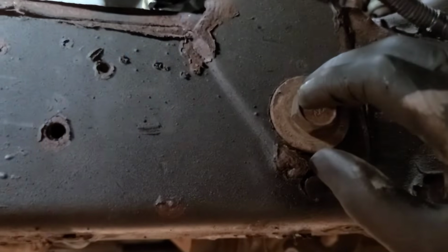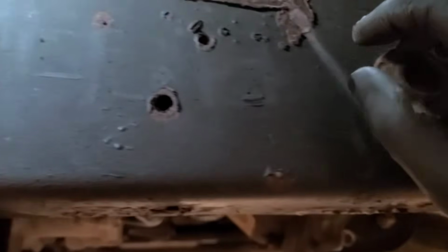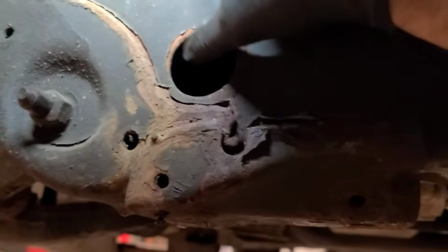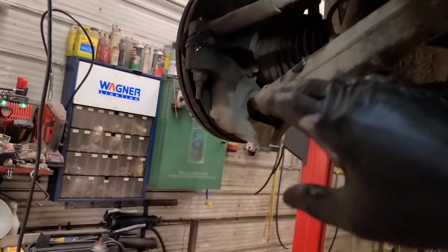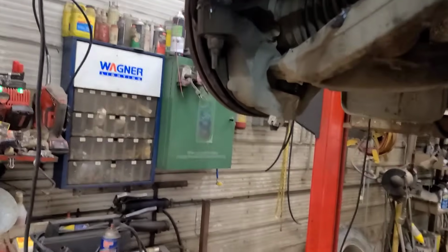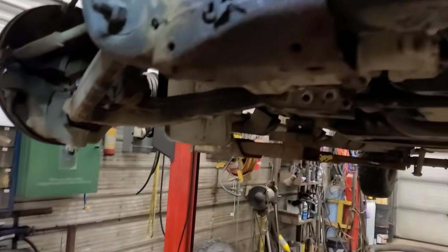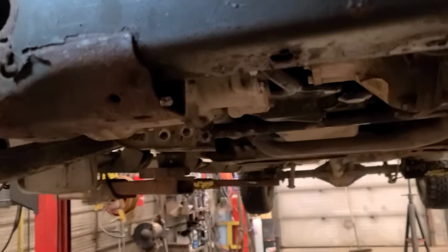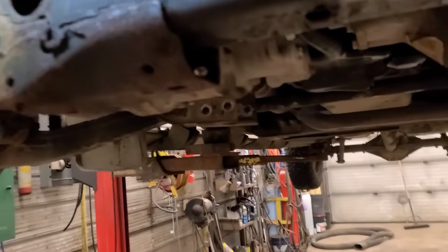So the steering gear is back in, the front differential is back in. Let's see, the front axle shaft bolts, put Loctite on them, 58 foot-pounds. The steering gear, the 2 large bolts here are 162 foot-pounds and 74 foot-pounds for these 2. The outer tie rod ends, 26 foot-pounds and 90 degrees of torque. What's left? Wiring harness is hooked up.